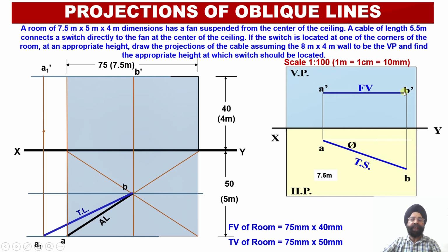So this really validates this particular aspect of the rotation of the line, that since our front view apparent length projection happens to be parallel to the horizontal plane, so this has resulted in obtaining the true length of the line in the top view. Now since true length was available, so by projecting it upwards, we have been able to obtain the apparent length projection in the front view parallel to the horizontal plane.